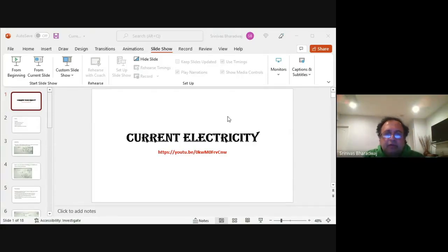So these are all the values, right? The first bar and the second bar, in this case, if it was Y and violet, that indicates the most significant and the least significant digits. So there are four bands: most significant, least significant, times 10 to the power of k. And then the last one is essentially the tolerance. So only the first three give you the real resistance.